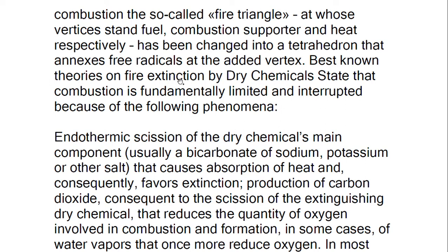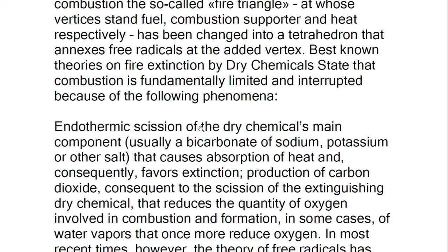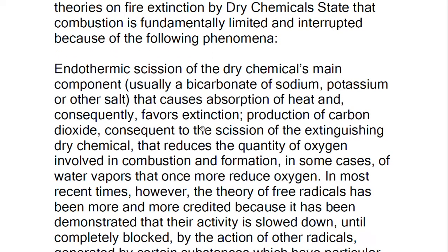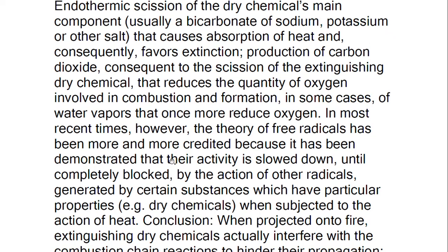Best known theories on fire extinction by dry chemical state that combustion is fundamentally limited and interrupted because of the following phenomena. Endothermic scission of the dry chemical main component, usually a bicarbonate of sodium, potassium or other salt, as we have already discussed, causes absorption of heat and consequently favors extinction. Production of carbon dioxide consequent to the scission of the extinguishing dry chemical reduces the quantity of oxygen involved in the combustion, and formation, in some cases, of water vapor once more reduces oxygen.